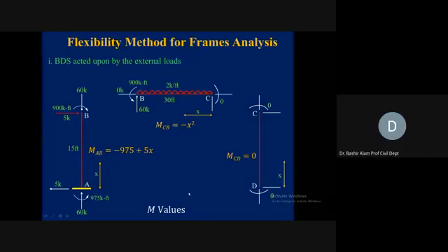And D. Now, if we start analyzing from the right-hand side, on the right-hand side, we don't have any load. So here, the axial force, the vertical line at D, is 0. The shear, the horizontal line, is 0. And the moment is also equal to 0. We need to keep this member in equilibrium. So nothing in the vertical direction at joint B, so it means in between we don't have any load, so nothing is going to be balanced at joint C. So at joint C, the vertical force, which is the axial force, is 0. Shear is 0, and bending moment is also 0.